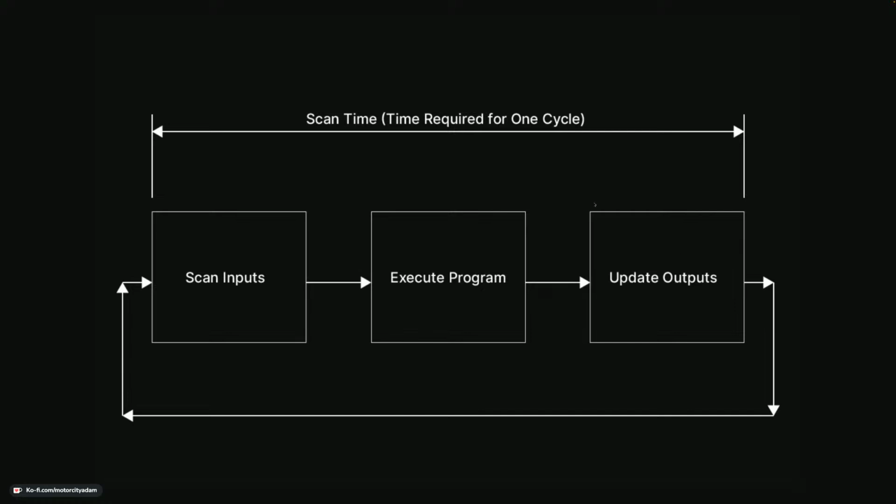understand what the upper limit of the scan time is, which can be influenced by the number and type of inputs that you're putting in and the outputs that you're supporting. So the controller itself is certified and structured from a software and hardware point of view such that the scan time is predictable given a set of inputs and outputs, types, and number.